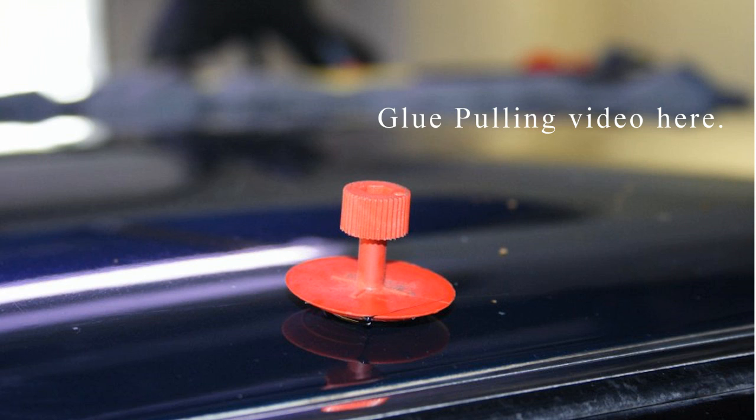One of the downsides of glue pulling is when we are dealing with some non-factory paint finishes, where the integrity of the refinished paint will not withstand the glue pulling process. When writing our estimate, the insurer will be advised of this. In some cases, they may still ask us to attempt the repair. If the repair is unsuccessful due to the paint delaminating, then that panel will need to be sent out for conventional repairs.